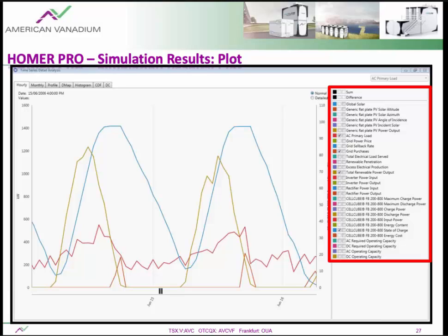As you can see with how the graph looks, PV picks up at around 8 o'clock, reaches its peak at around noon, and starts dipping from there. Following that, you can see the CellCube system starts picking up as soon as the PV energy surpasses the load, and it starts discharging when the PV dips below the load.